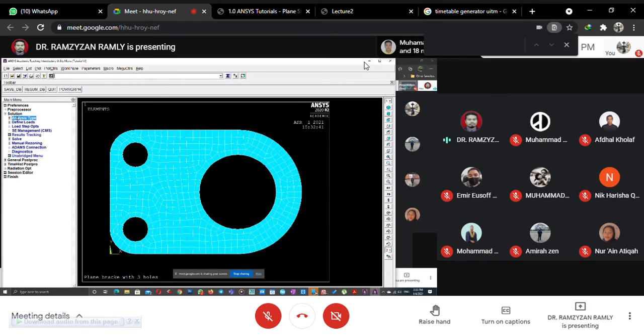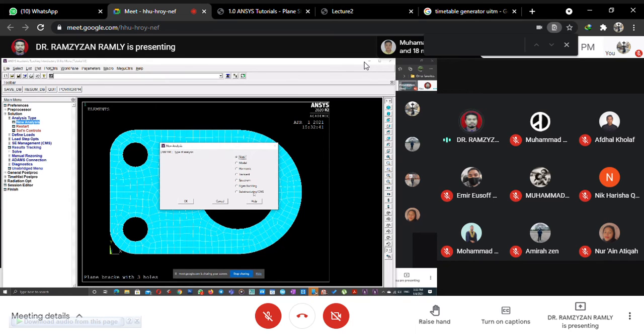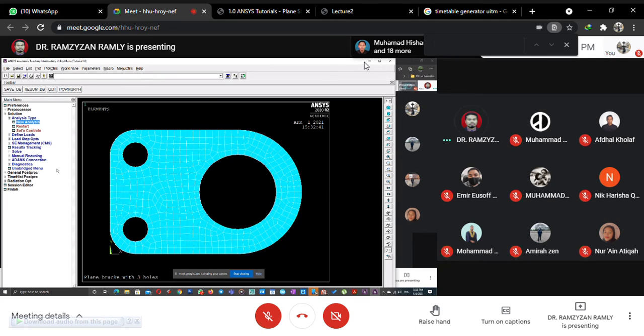Okay, the analysis type, we have a new analysis, which is a static analysis. Press OK, and then we can define loads. All right. For loads, this is the boundary condition.